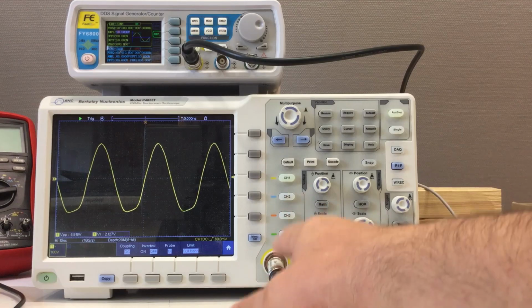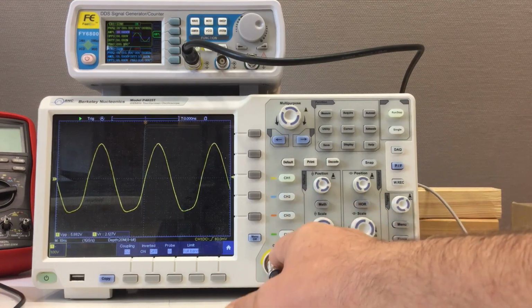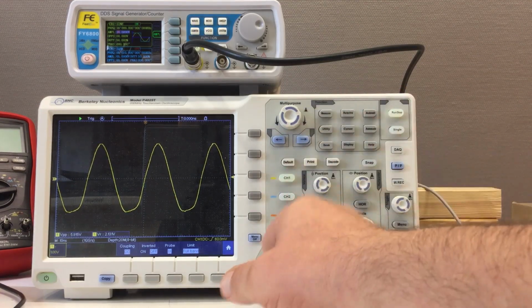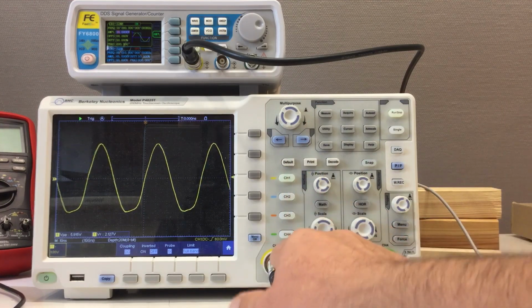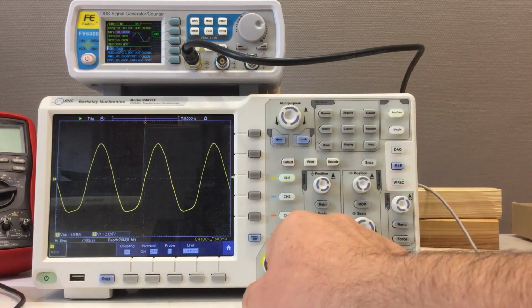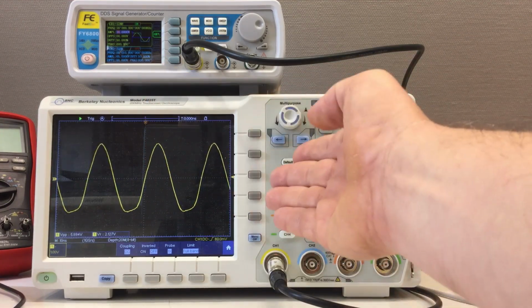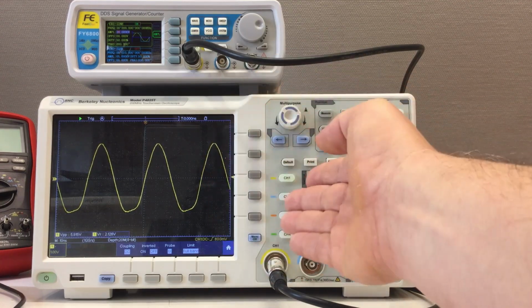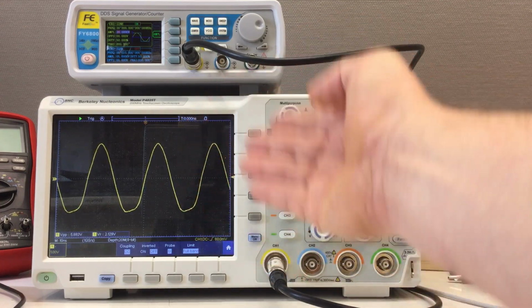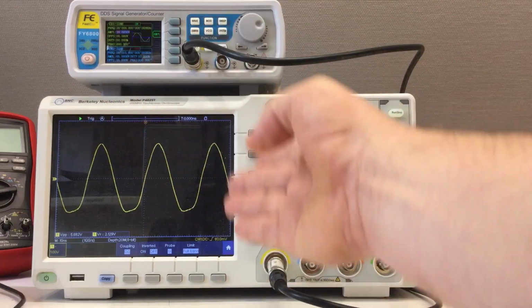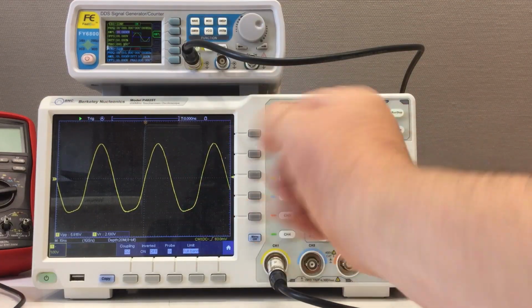That is, you put a 50 ohm external load on your unit, as we had before with resistors at 1 kilohertz. But we already know that we can drive an external 50 ohm load only up to a set voltage of 10 volts peak to peak.